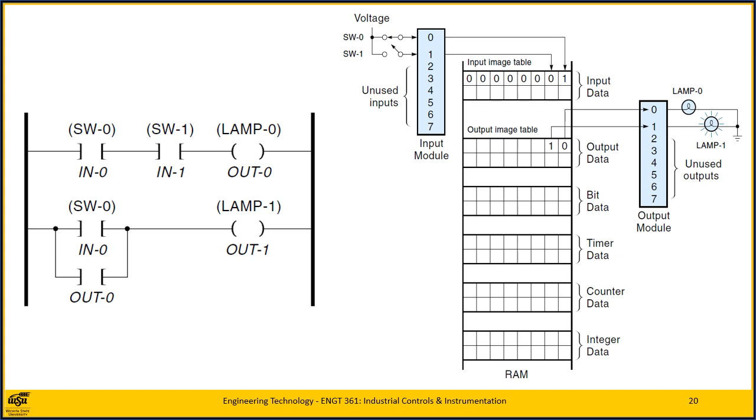Looking over the process just described, some observations are in order. First, the PLC accomplishes its control mission in the same way that all digital controllers work, by executing a loop, a scan, over and over again. For the PLC, however, the looping action is automatic and does not have to be programmed. For each scan, inputs are read in, outputs are calculated based on the inputs, and then the outputs are sent out to the real world.